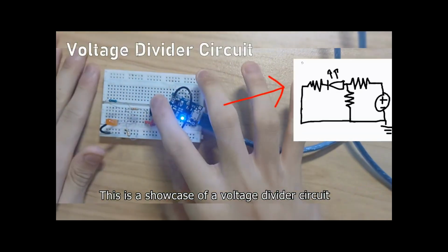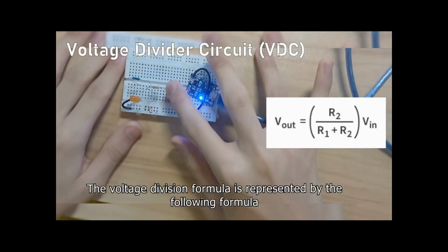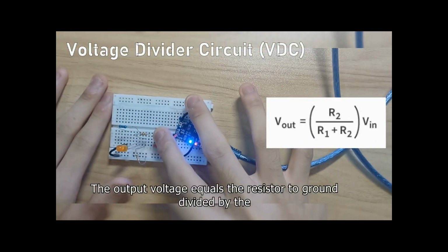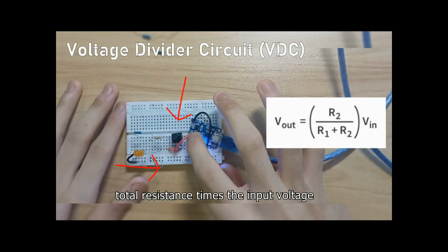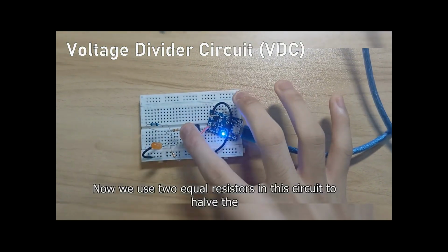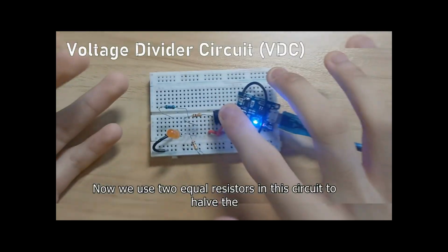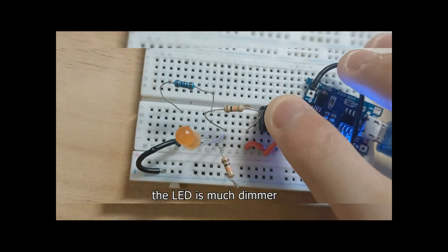This is a showcase of a voltage divider circuit. The voltage division formula is represented by the following formula. The output voltage equals the resistor to ground divided by the total resistance times the input voltage. Now, we use two equal resistors in this circuit to halve the voltage. As you can see, the LED is much dimmer.